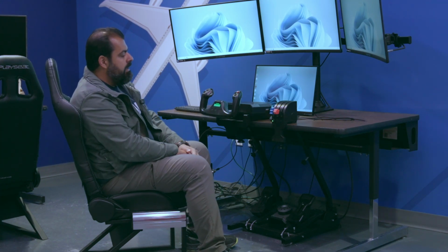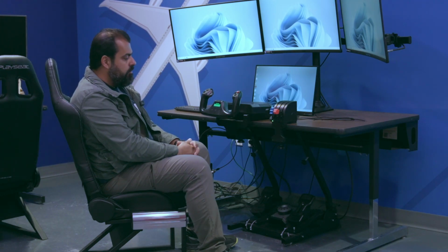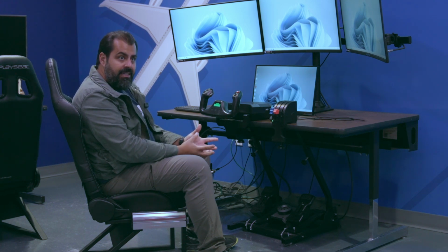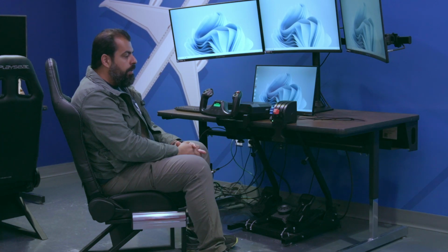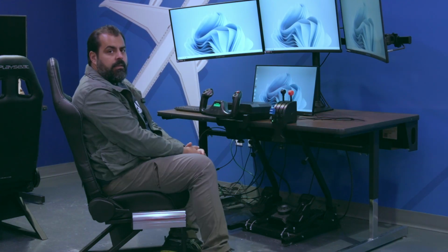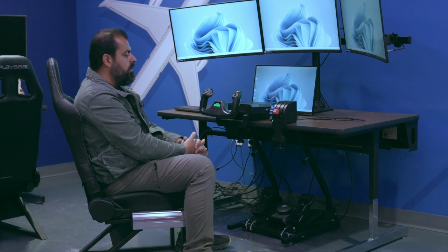But the other two levers are the throttle control and the mixture control, which control how rich or lean the fuel you're providing to your engine is, and how open or closed the throttle is. When you go full in, you're providing the maximum power, and for no power, you want to make sure these turn back to zero.